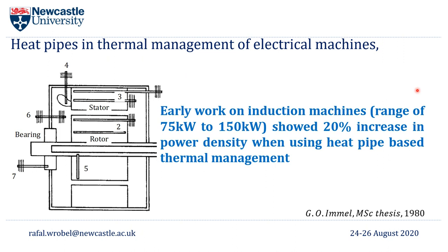In general, the early work was focused on induction machines, and the power range of the machines analyzed at that time was somewhere between 75 kilowatts and 150 kilowatts. That early work demonstrated reasonable performance benefits, with a 20% increase in power density.